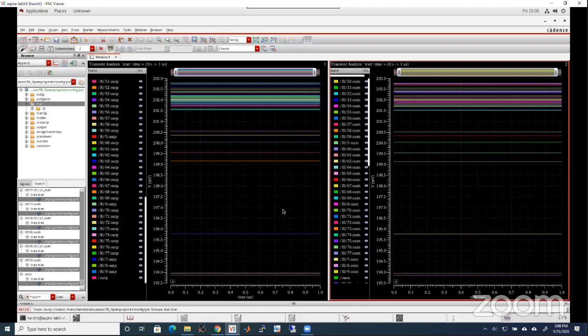So this is one of the smallest simulations. We saw that it runs very quickly and gives us a lot of information to show how good our design is. I have never seen a lot of people skip this simulation. In industry, you cannot build a chip without doing this kind of simulation. So please keep in mind, these are small simulations that are very, very important. How balanced is the output of the op-amp? Especially if the op-amp gain is very high, you have to make sure that they're perfectly balanced.